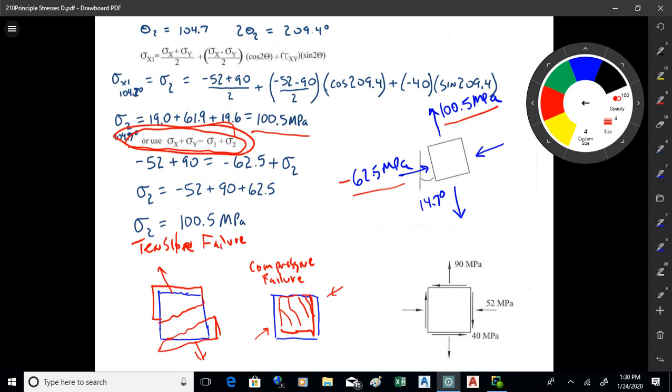You know, because you could conceivably have sigma 1 is 50 megapascals, and then sigma 2 is negative 70 megapascals. Is that much tensile stress at that angle? So at another angle, it might not necessarily fail. Yeah, right. That is the angle at which the tensile stress maxes. Every angle has its own different tensile stress or different stress on it. This is the one that is the biggest, and we figured out where it is and how big it is. Right. Okay.